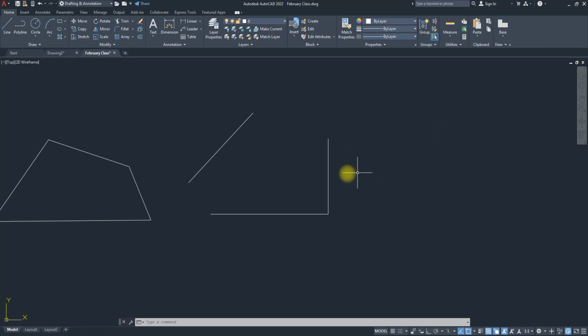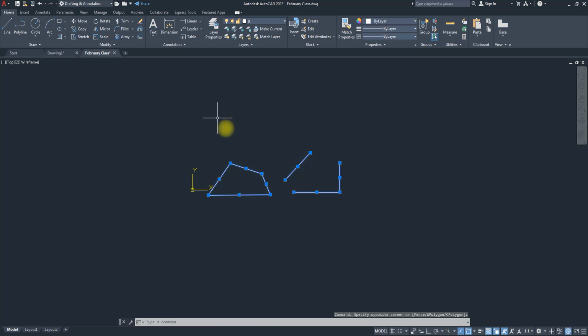Right? So let's now look at the different ways we can draw in AutoCAD. The first one is the coordinate system. So let's try and create a line and work with the coordinate system. We have the point, we have the location, so we don't have to be clicking. Since we know the location in the graph, all we need to do is start inputting those locations. We'll start with the absolute coordinate system of the L shape. Once we are done with that, we'll do absolute relative, relative rectangular and relative polar. So let's start with the absolute coordinate system.